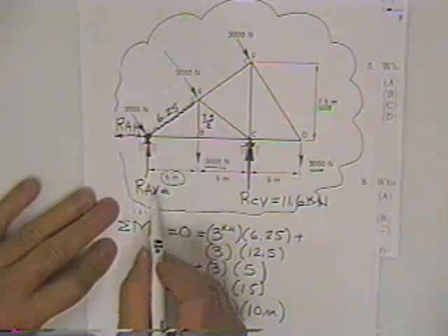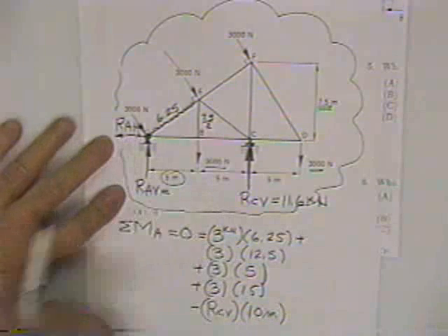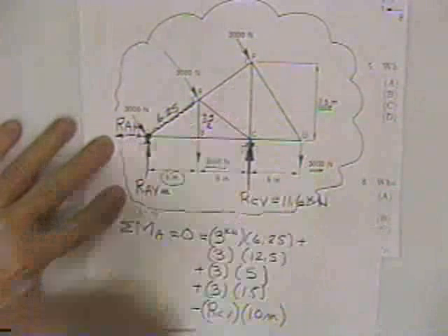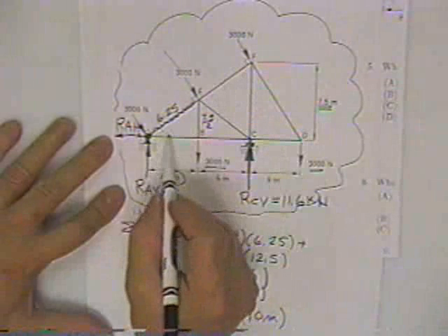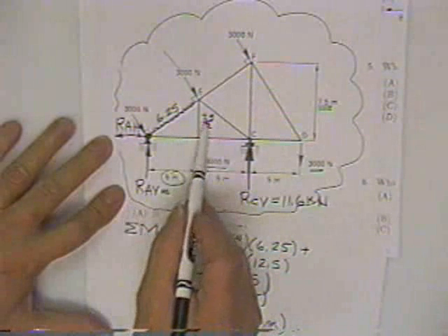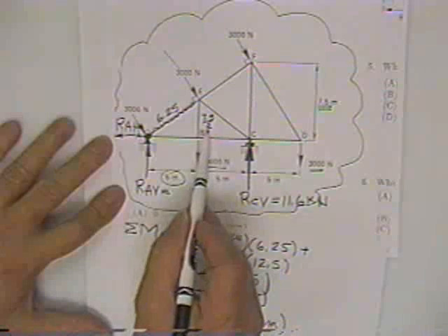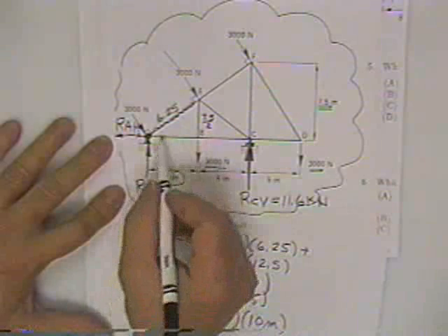Then you get sum forces vertical and get this one. Now, getting the sum force horizontal, you're going to have to break these down into components anyway. So that means you're going to have to find this angle, and that's easy now. Who has an angle 7.5 over 2 divided by 5? That's opposite over adjacent.